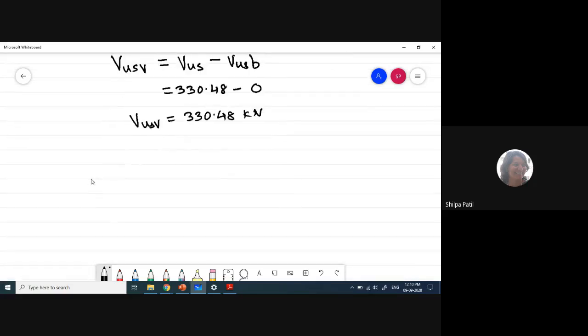Now when we provide the additional shear reinforcement, we assume some diameter of these stirrups, and normally we provide two-legged stirrups. So what is the meaning of two legs? If this is the cross section of your beam and these are the main reinforcement, in our case there are 4 reinforcing bars. So I have drawn 4 circles over here, and some minimum reinforcement in the compression zone also we provide. Normally it is two bars.